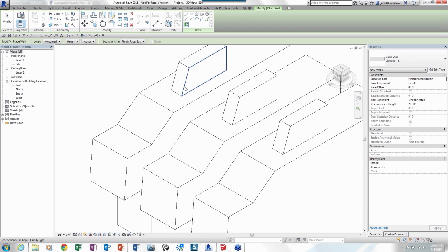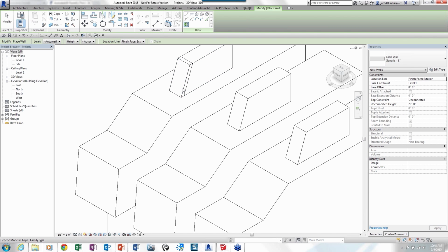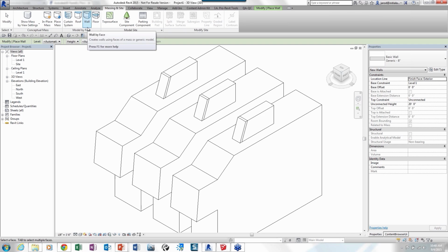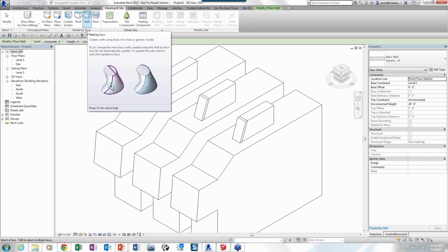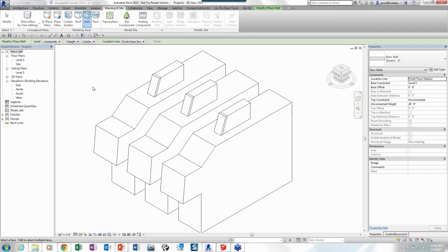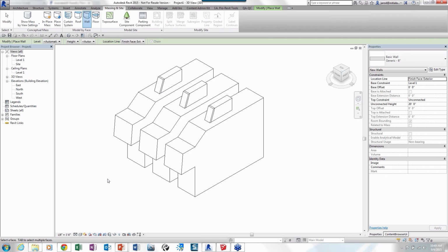You can come over, you can choose whatever wall type that you want to use. We all know how to build walls if you've worked with Revit. And then the big thing is you can start picking on those surfaces, which then matches to that, which is really cool. And you can go on and on with this thing. But that's the idea of taking something that you've done in FormIt at whatever detail level, and bringing it in and building forward, so we're not throwing anything away.